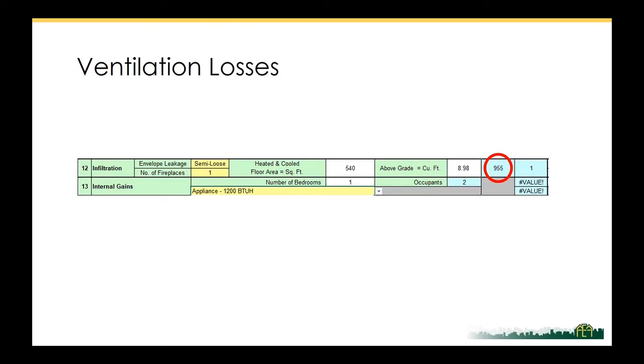If there's existing cooling, it's pretty negligible, but it's still a hit that we have to consider. But yes, you are correct, you do receive a hit when you install LEDs versus incandescents, and internal gain is something that we should consider. We'll get into that on the passive house side. Okay, continue. Sorry. Thank you.